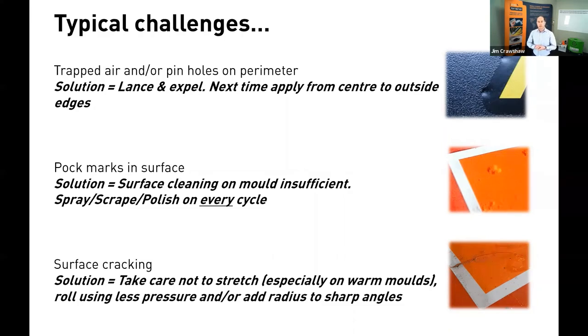Now what that is is what we saw in the ZD video. If we don't lance and expel any trapped air bubbles, you will see these sort of results. So just take time next time to apply carefully from the center of the graphic outwards to the edges to avoid trapping air. The second one I'm showing there is pock marks in the surface. So these are like small craters, and these could be the size of a pinhead to the size of the end of a ballpoint pen.